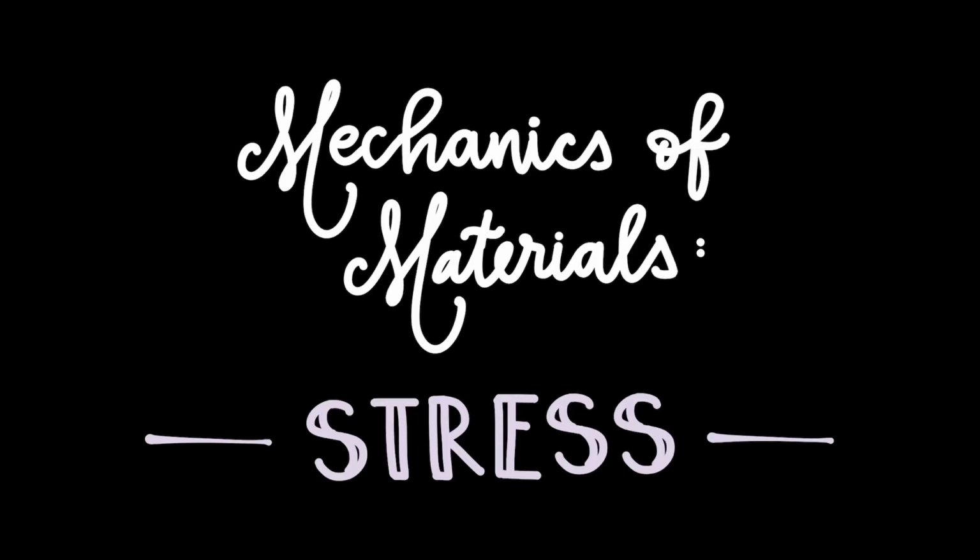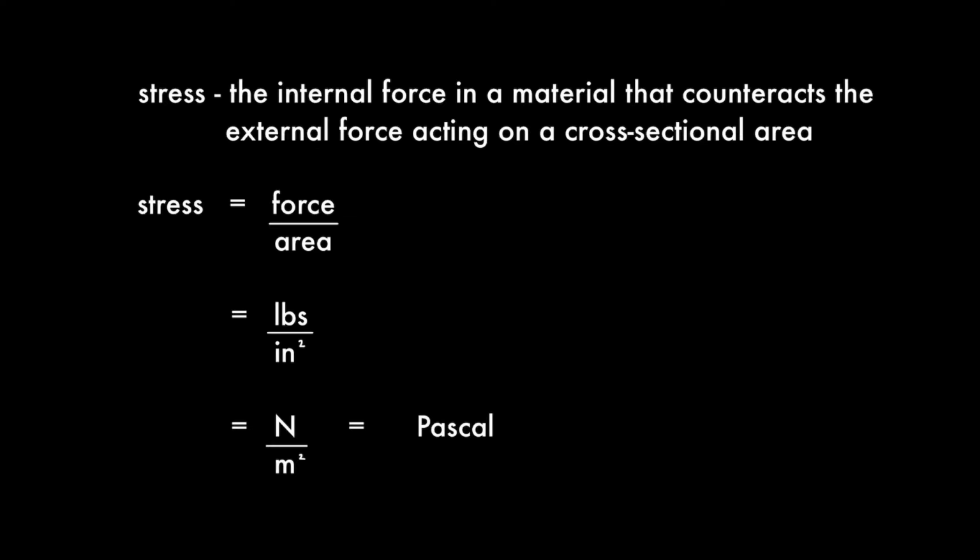Almost all of us have experienced stress as a result of demands in our lives, but let's examine stress as we know it in the engineering world. Stress is defined as the internal force in a material that counteracts the external force acting on a cross-sectional area. Now, that's a pretty lofty definition, but it's essentially a force per unit area. So the units of stress are usually written as pounds per inch squared or newtons per meter squared, which is also called a Pascal.